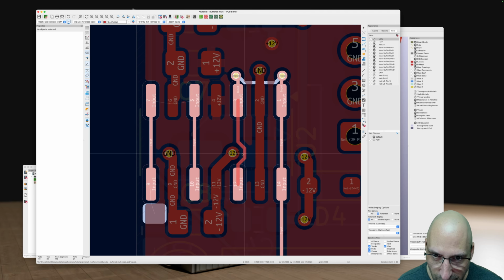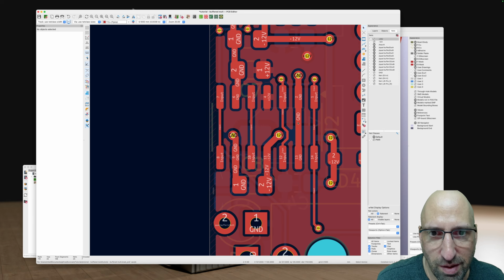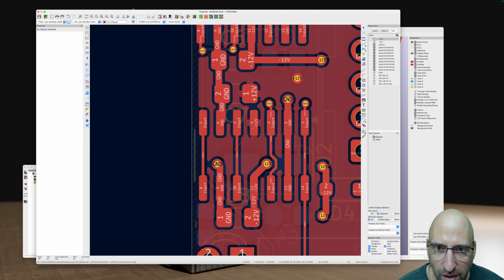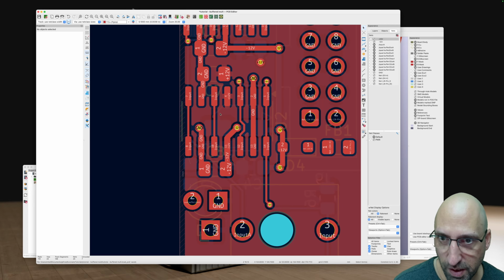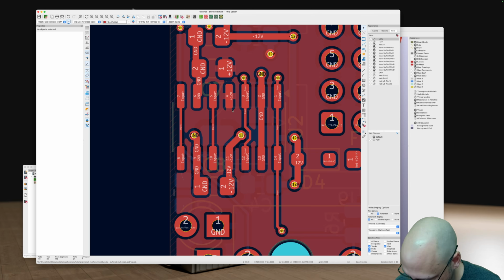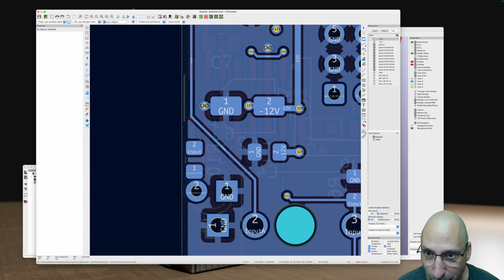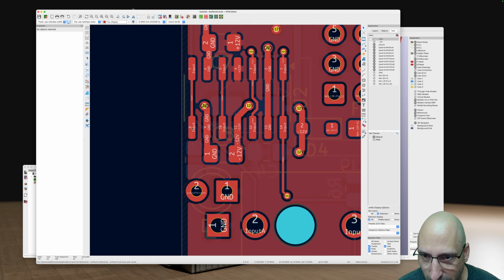to fill the zone. I like relatively uninterrupted copper going in between. Yeah, because here we've got a break, there we've got a break, but there it is coming, that plus 12 volt coming through. So, yeah, it's kind of important. I mean, if that does get isolated completely, then it's going to show up, hey, there's a new rat's nest line you've got to connect. So it won't just happen without warning, but yeah.